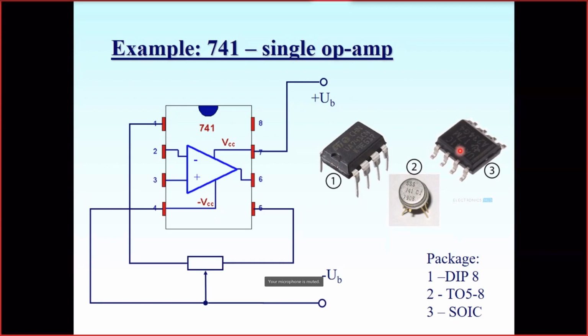And the third, quite old-fashioned, is the TO-8 housing, this metallic box, but it has some advantage: the metal of the housing protects the internal circuitry of the op-amp from electric interference very well. Such a type of housing is still sometimes used.